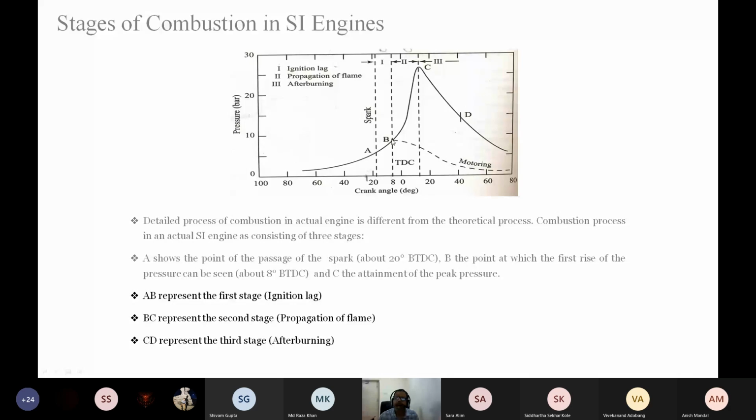Noticeable pressure can be detected with your sensors, and you will find that since it is a motoring pressure, there is no combustion. So the pressure will fall immediately as the piston comes down. But the thick line is the firing pressure. The pressure is rising because of the combustion taking place inside the combustion chamber. The pressure and temperature inside the combustion chamber will move up even though the piston is going down, and it will reach that point, the peak pressure, which occurs at the corresponding crank angle.